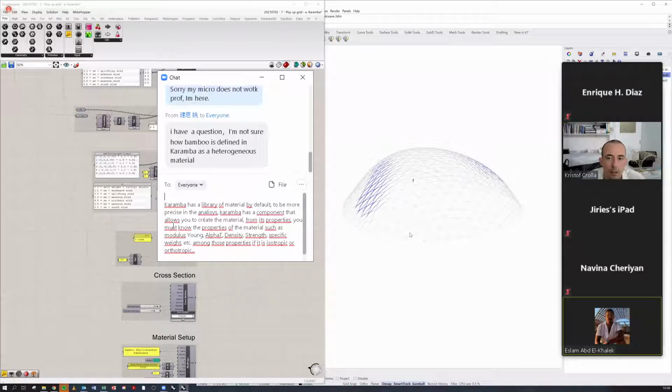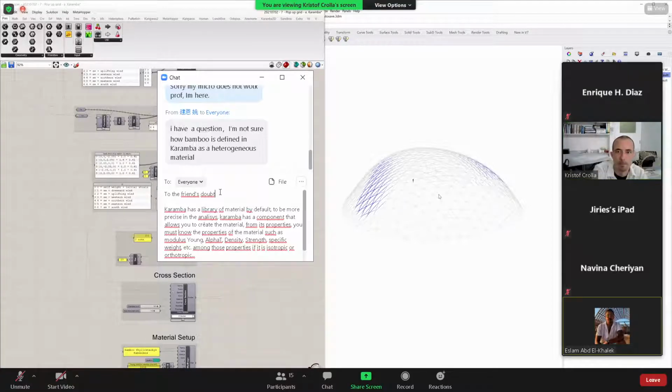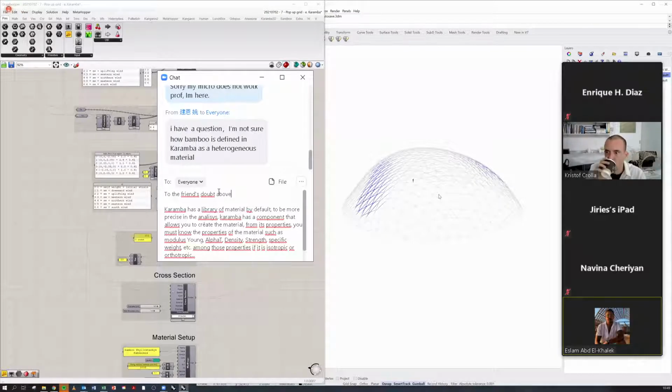But it can affect the uplift load because it closes all the structure perforation, so the uplift load will increase. Well, in the current calculation model here, the uplift load is entirely based just on the area of the mesh, as if it is connected everywhere to the bamboo structures underneath it. So the mesh is directly affecting the loading, but it's not helping in the structural response. Okay, thank you. Other points? But good points. Very good point. Thank you so much.